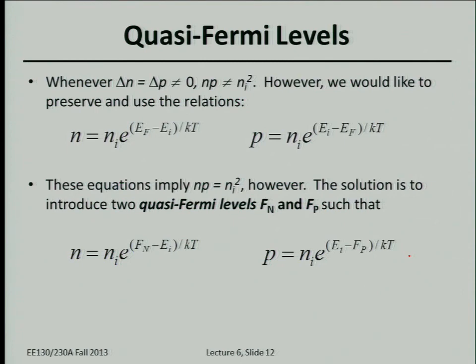But practically, why do we even keep track of the Fermi level in an energy band diagram in this class? Yeah, we keep track of the concentration of carriers with the Fermi level. So in thermal equilibrium, there's one Fermi level in your system. In other words, one Fermi level can tell you the concentration of electrons and the concentration of holes.